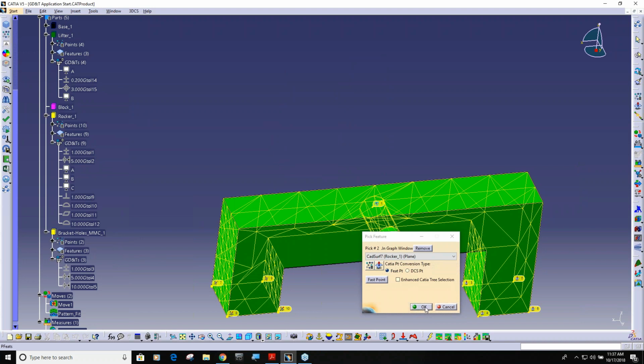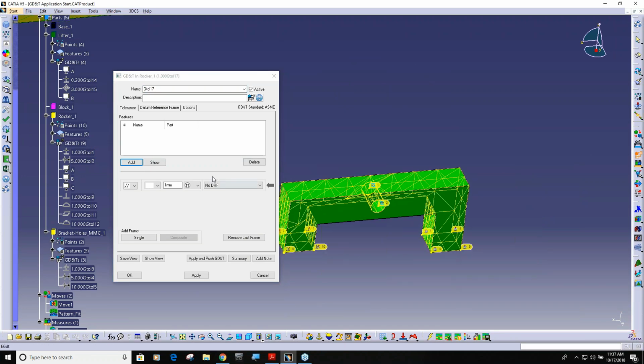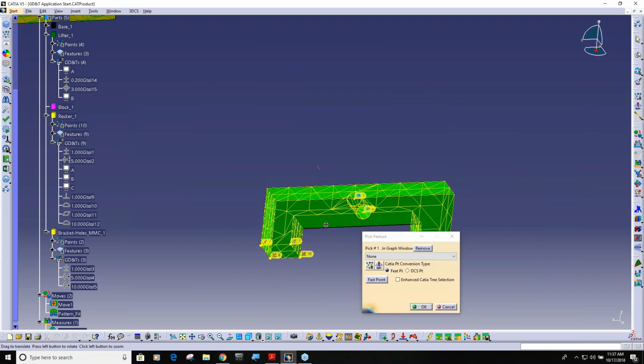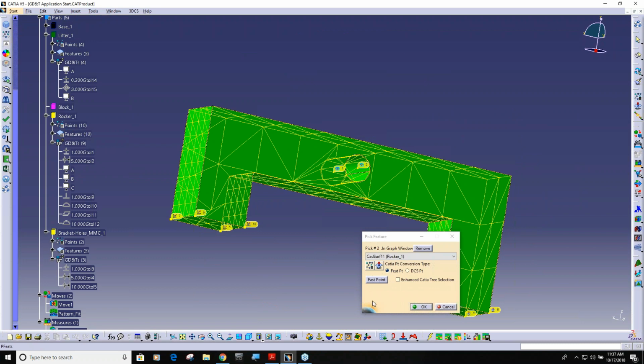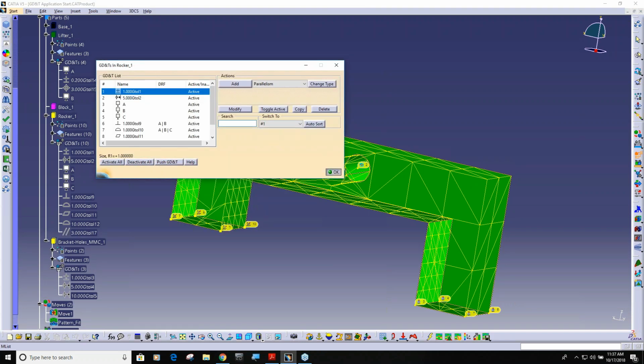Oh, that top surface was datum B, wasn't it? Sorry, I don't want to do that. Let's add it to this bottom surface. So I got parallelism. I'm going to say 3 millimeters so I can see something. And I'm just going to say, okay.